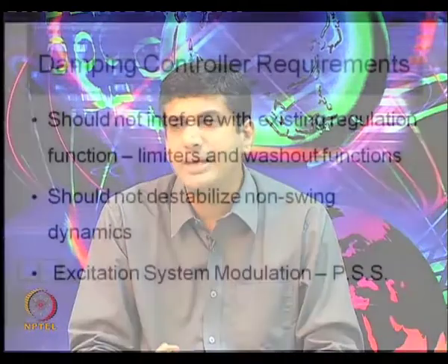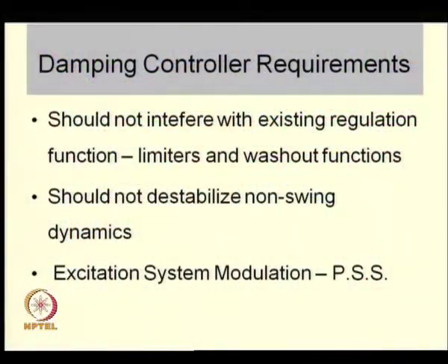So, what exactly would you expect from a damping controller? When I say I will augment my control, there are of course certain constraints which should be kept in mind. For example, the damping controller should not interfere with existing regulation functions.